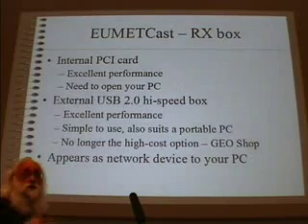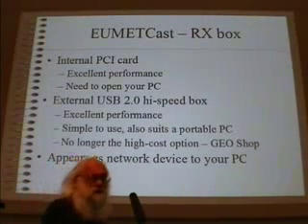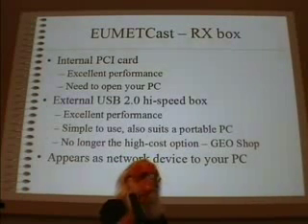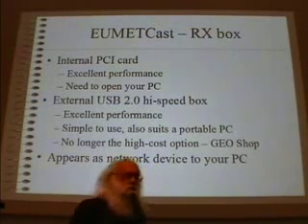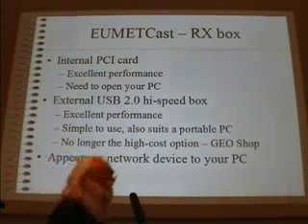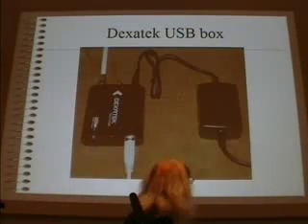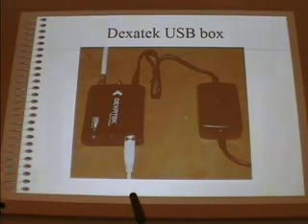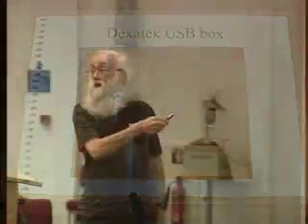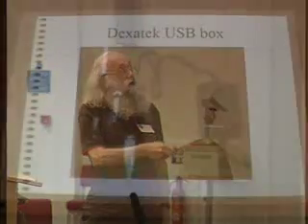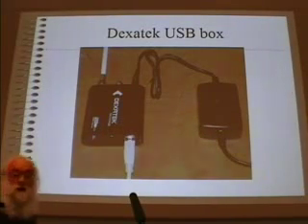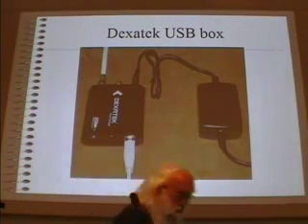To receive now, you used to have to open up your PC. Some people would be dubious about it. Open up the PC, oh dear, it's a little sticker on the back that says do not open. But you don't need to do that anymore now. You can get a little box. This one's a DEXAtech box. And really simple, you feed 12 volts in, you feed the 1.1 gigahertz in, and you get USB coming out. And rather like my mouse, it has a bright blue LED on, so it must be working.